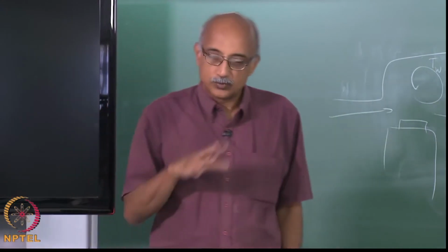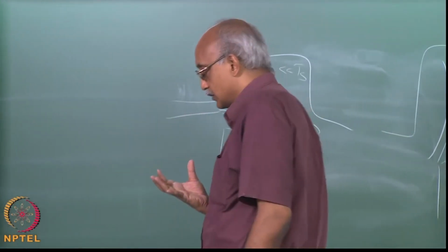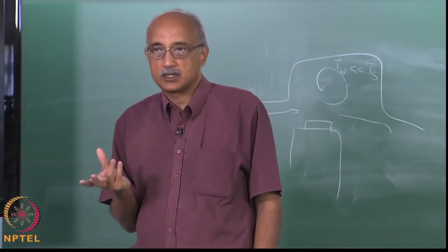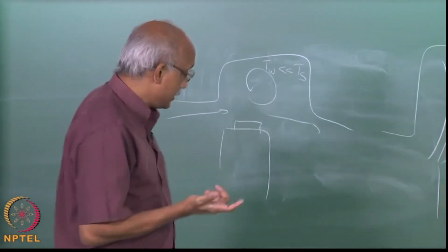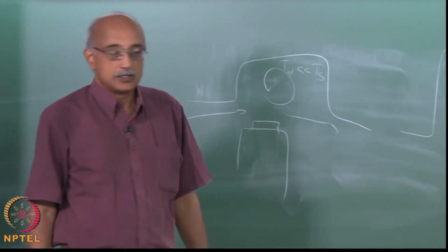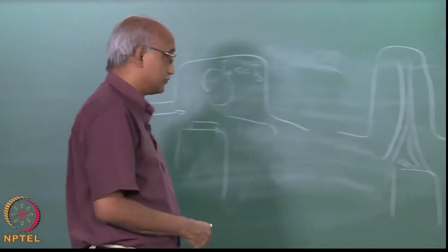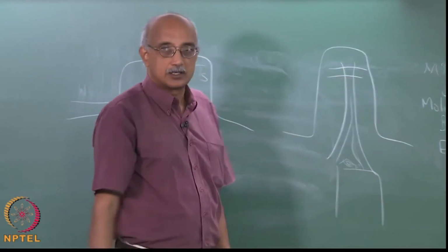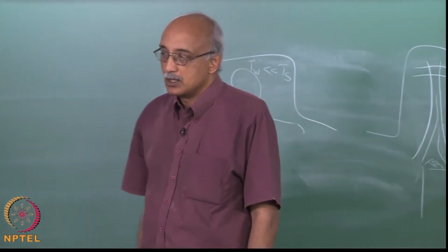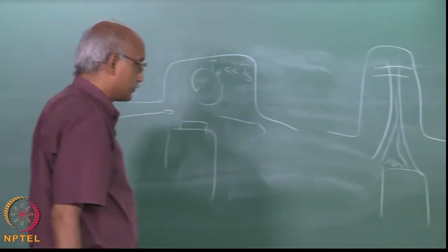So, it is not only the flow dynamics that result in turbulence, it can also simply be the physical design of the CVD reactor that can result in unintended turbulence effects. Now, again, the horizontal flow design is much more susceptible to this compared to the stagnation flow design, because the path from the inlet to the substrate is essentially a straight line in a stagnation flow reactor. So, the geometry of the reactor itself does not play a significant role in controlling the deposition of the film.